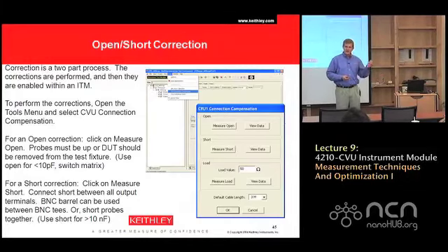What we do is generate and send a pulse down what we call the current terminal, or the force terminal, and that pulse goes all the way down, comes back on the sense terminal, and is sensed with our sense voltmeter. Because we know precisely the timing of when we made the pulse versus when we measured it, we can measure the entire time of the round trip.